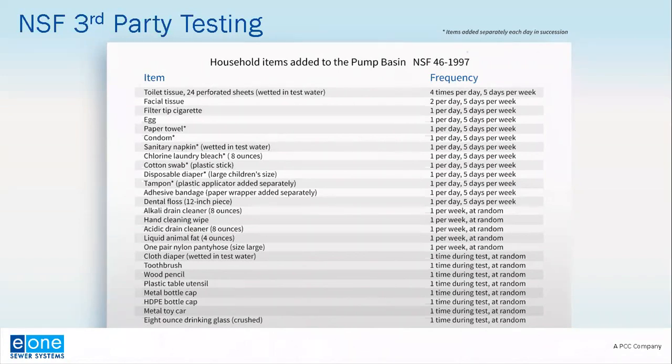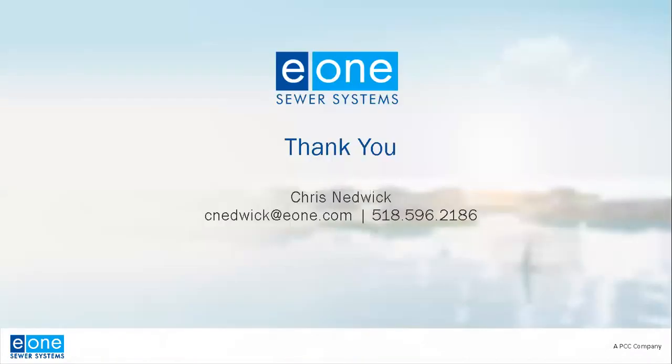You can see that it calls out a specific item to be entered into the station with a specific frequency. This is a random test. Some of these items, for example, are toilet tissue or facial tissue, egg, paper towels, and so on, all the way down to metal toy cars, which are Matchbox cars, wooden pencils, toothbrushes, things like that. You'll see on the right the frequency that those have to be added. Basically what this test gets down to is whether or not our pump can deal with all of these things without jamming, which it certainly does.